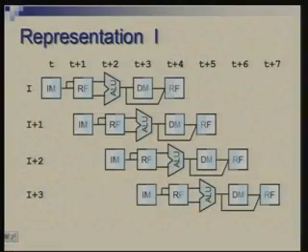Then a divide instruction will be in this stage, the ALU stage, for several cycles, and the instructions which are following it will get held up. So the pipeline will see a structural hazard or a resource conflict either when two instructions are trying to utilize the same resource because of non-linearity in the pipeline, or because some stages take longer and some stages take less.